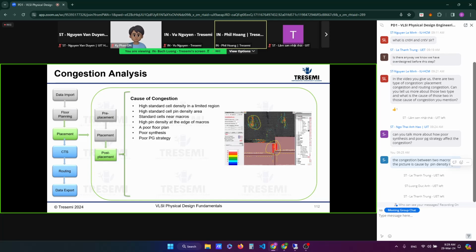But if it's coming in at 70% and you over-design your power grid, so that part of the tracks are covered by the PG network, then the amount of routing resources is not as big as you think. That means if you have too dense of a power grid, then the incoming utilization should be lower than 70% to compensate for tracks being lost by the over-designing of the PG, or power ground grid.